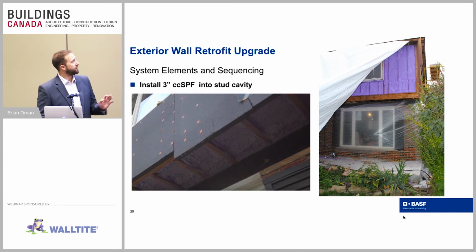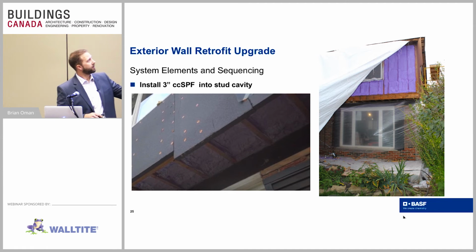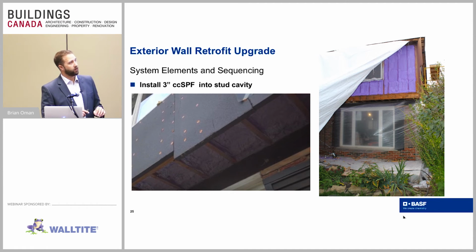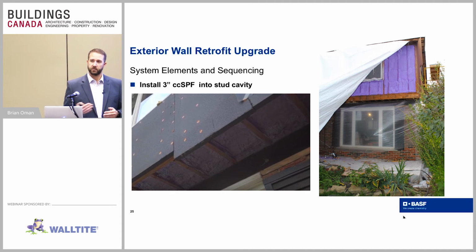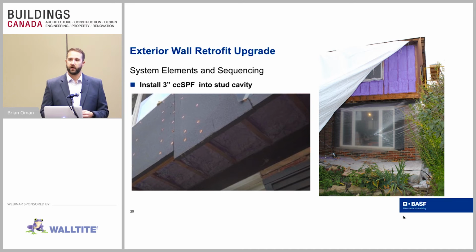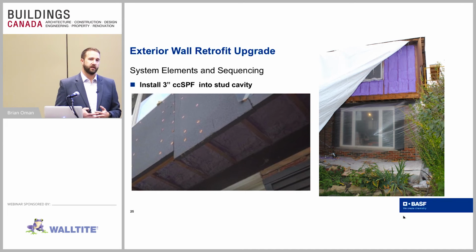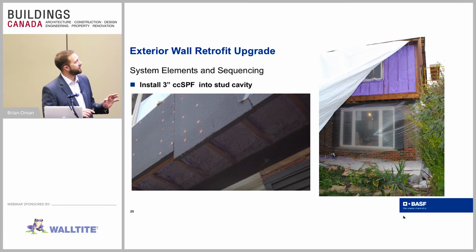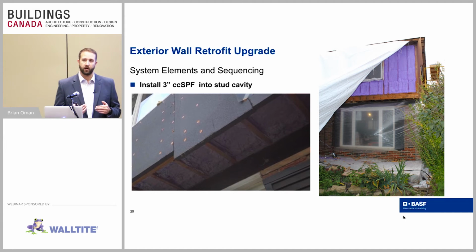So, kind of hard to see with the lights here. This is an area we want to showcase, and this is going to be part of that cantilever. So this is a floor system that's now overhanging that first floor and is going to be prone to being cold, especially in the wintertime, right? So in this case, that cavity has now been completely sealed off and it's been well insulated with the closed cell foam.